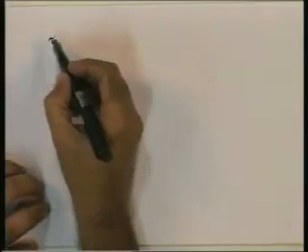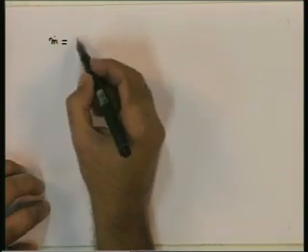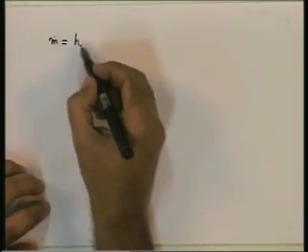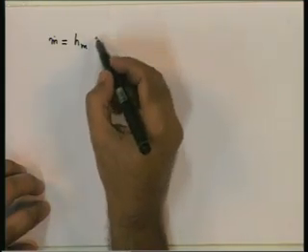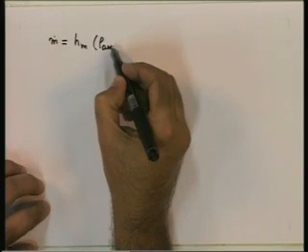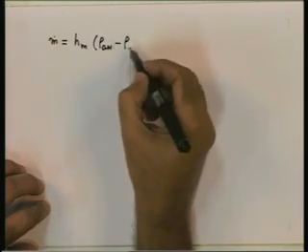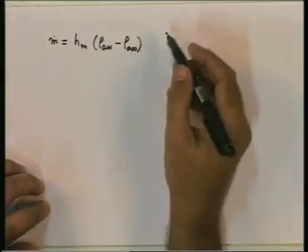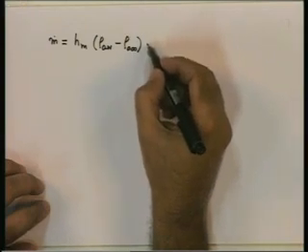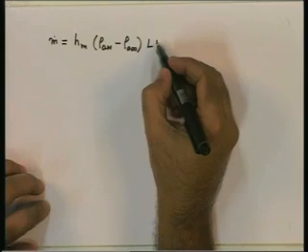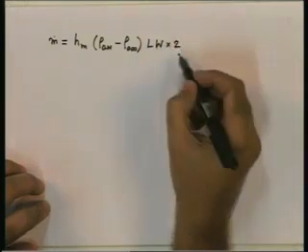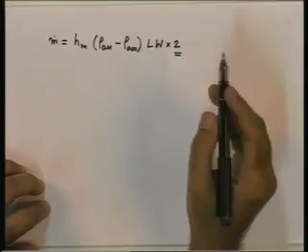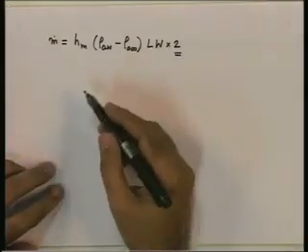Now we have the mass transfer coefficient, we have the density difference, so the mass flow rate will now be calculated as mass transfer coefficient Hm multiplied by rho A W minus rho A infinity, that will be the mass flux, multiplied by the area, which is L into W into 2, because both sides of the plate are wetted and the air flows over either side.